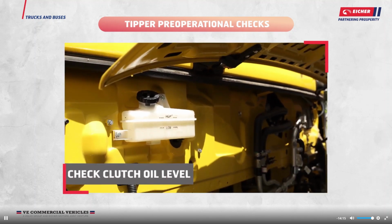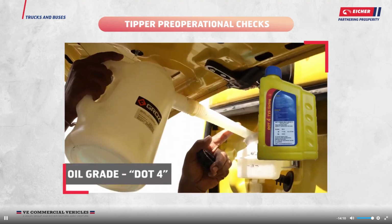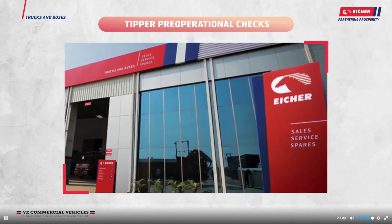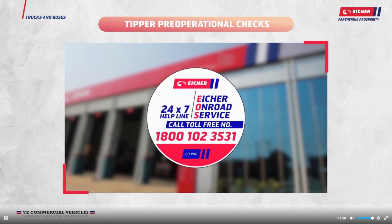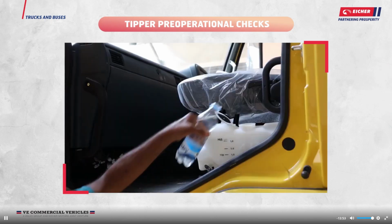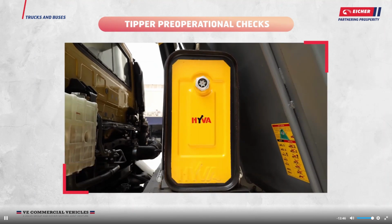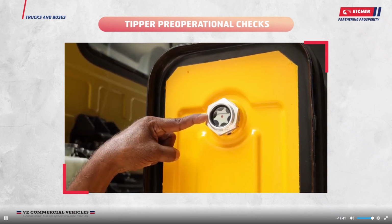Check clutch oil level. If the level is low, top up with recommended grade oil. Caution: if the clutch fluid is excessively low or if any leakage is suspected, get the vehicle inspected and repaired at an EICHER authorized service center. Check water level in the windshield reservoir. If level is low, fill with fresh water. Check tipping system oil level in the reservoir tank. Check oil level through indication glass provided on the hydraulic tank.